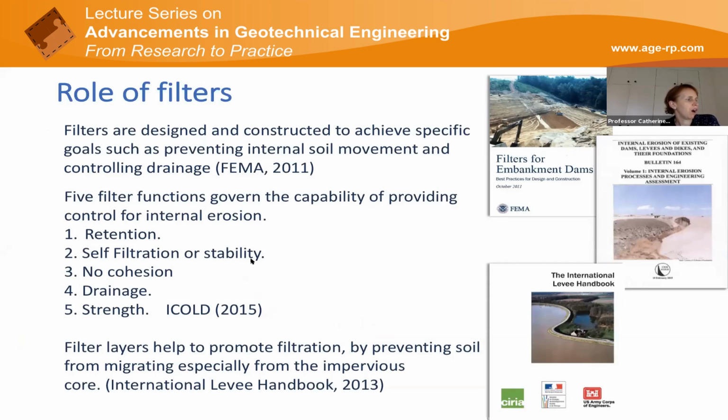And if we look at the ICOLD bulletin on internal erosion, we can see that filters have functions: they have to retain, they have to be able to be internally stable themselves, and they need to provide good drainage. And in our work, we've been looking at these three aspects of filter performance because they involve thinking about the material at the particle scale perspective.